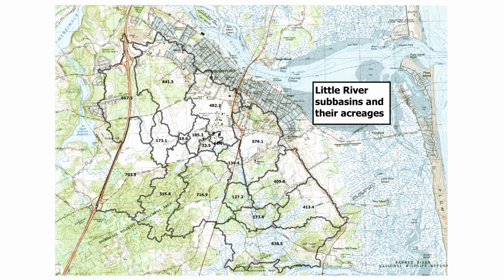I used Quantum GIS and very powerful GRASS GIS software to perform automated subbasin delineation using the digital elevation model brought into it. The digital elevation model for the Little River work that I used was the USGS 2011 LiDAR for the Northeast.